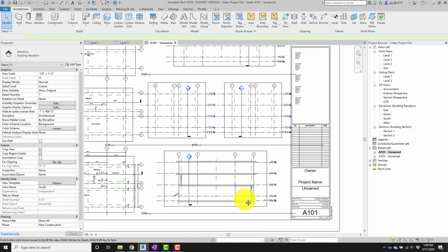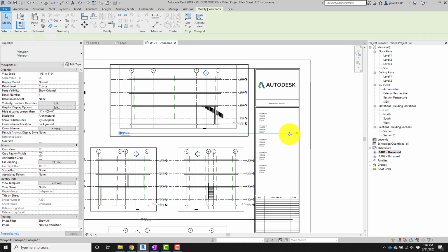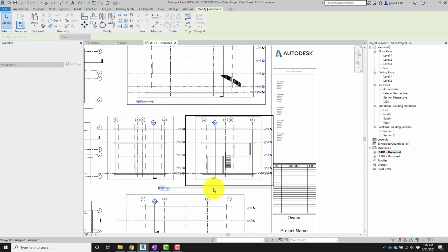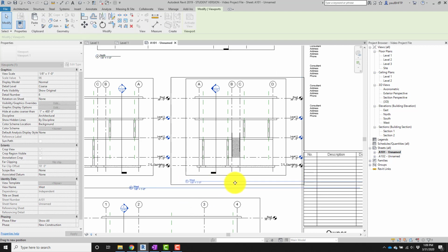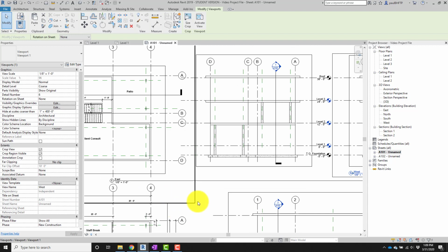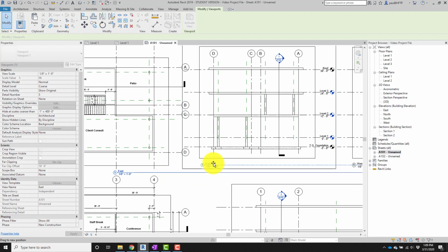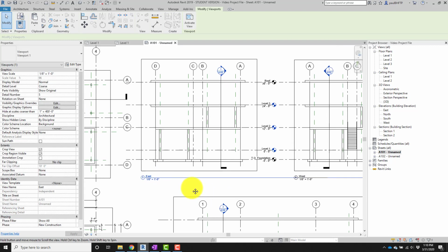Like so. And then again, I will move the tags for the name down below, just to the bottom left hand corner of each view. So to move these things, I click once on the line itself, and then I can click again and hold, and I'm dragging it over. You can see it snaps to a line with the name on the right, and then I let go to place it.